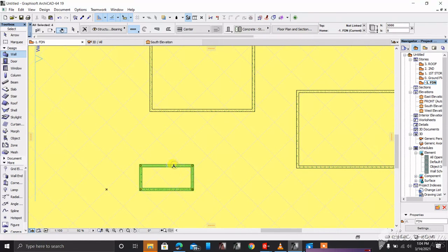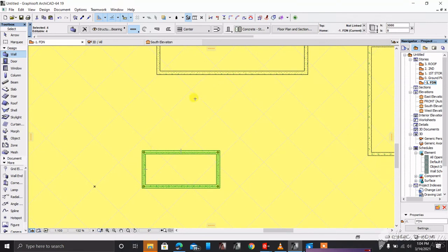So we'll realize that when you use a chained one, both of them will be linked. So if we want to unlink, once we hit ctrl+shift, then we select the particular wall, you come up here and we suspend all the groups. You can use a command line, alt then G. Once you do that, you should have suspended all the walls. As you can see, I am able to select all.